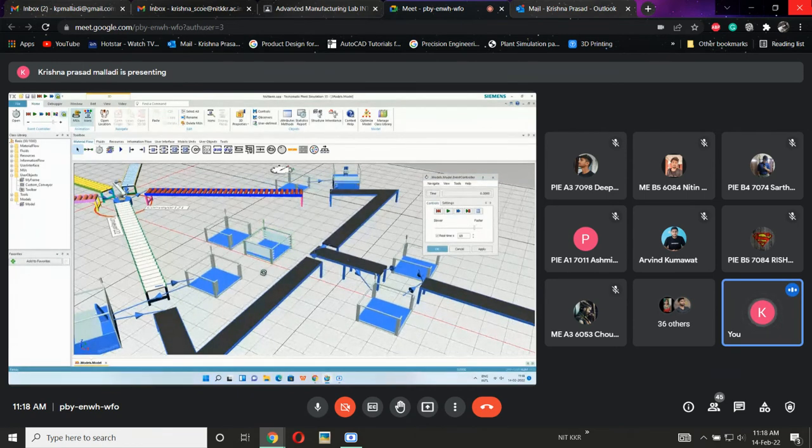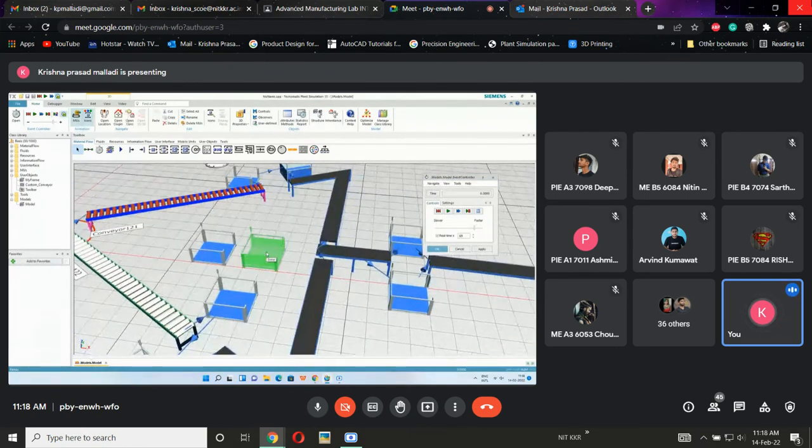Generally, we don't use this type of sorter in Plant Simulation. We only use this condition. Why? Because in general, when the first part enters the conveyor, we think the part that entered the bin first needs to exit first. That is the condition given to this buffer: first in, first out, the default condition. That is why we use this buffer as the default one. This buffer also uses the same principle: the material that comes first will go out first. Clear?